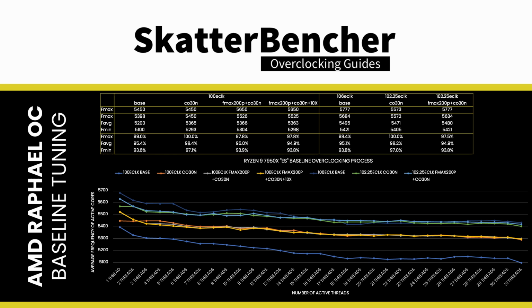The base case with E-clock frequency ranges from 5684 MHz at one active thread to 5436 MHz with 31 active threads. The programmed Fmax is 5777 MHz, which means our effective Fmax is 98.4%. The average frequency is 5495 MHz, 300 MHz over base case, and the minimum frequency is 5421 MHz, 320 MHz over base. Then further fine-tuning can begin.